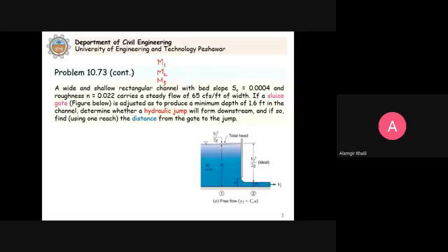You have to compare the depths, because the subscripts 1, 2 and 3 represent the type. M1 means that we have a mild slope or channel and the depth is above the two. Which two? The critical depth and the normal depth. When it is between the two, we say type 2 profile. And if the depth in the channel is below the two, the critical depth and the normal depth, it is an M3 profile.